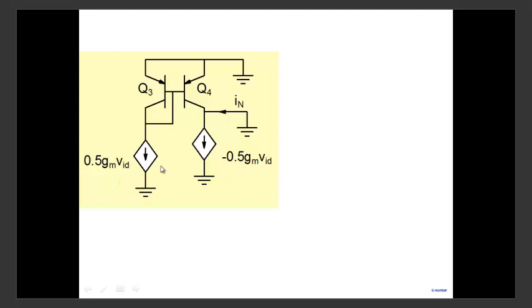So, this current, where will it flow through? Obviously, if I look at the Norton's current, what are the contributions to the Norton's current? Can you see? One is this current. Of course, a part of this current flows here. So that's there. Where else would Norton's current come from? From Q4. Q4 will also give rise to a current. Why will it give rise to a current? Note that this current that you see here will flow through Q3 and it will develop a voltage here at this particular node. It's a small voltage, but it will develop a voltage here. That voltage will go here to Q4.